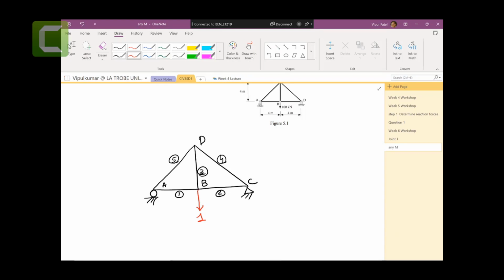Again, there are no rules. This one that I put has no unit. This is just a virtual, dummy load. There is no real load. This is just to trick the system, right? So we put 1, no unit, a 1 unit load. So when we get the answers, we don't need to scale or adjust anything. If you put 10 here, then your displacement would be multiplied by 10, and you would need to divide by that. Keep in mind there is no rule for why I put 1. You can put 2. This is a dummy load as I mentioned, but your displacement would be doubled if you put 2 here. To keep the mathematics simple, we keep it 1.